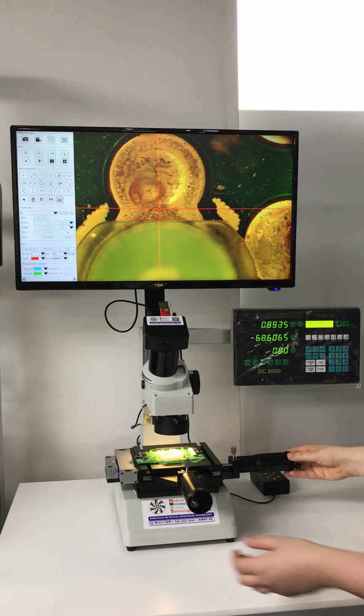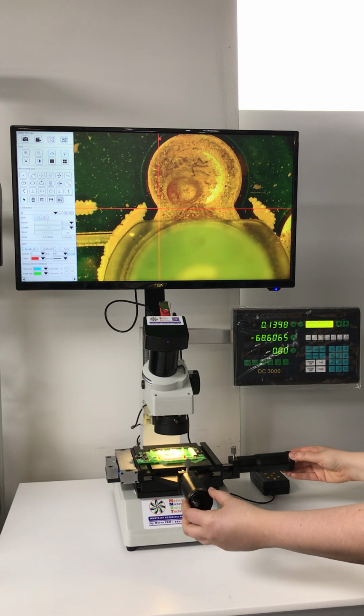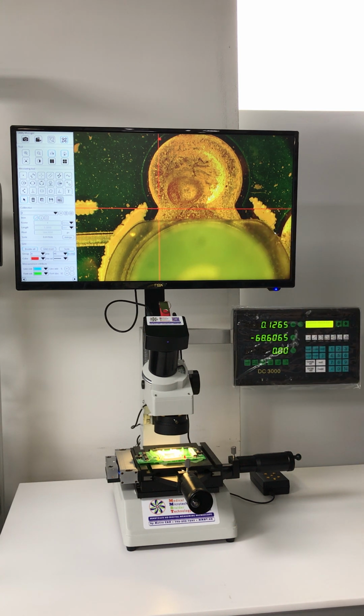Now let's do the next measurement. Let's do a line. When you are measuring, bring the point that you want to measure into the crosshair. That will be the reference point that it'll take. And again, please use backlighting if you have parts with shadows so you can get a more accurate measurement. So we'll press the line.